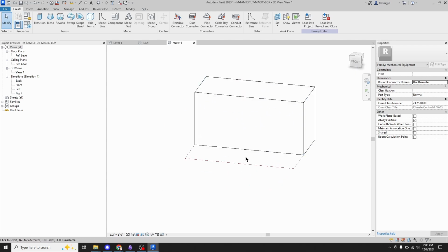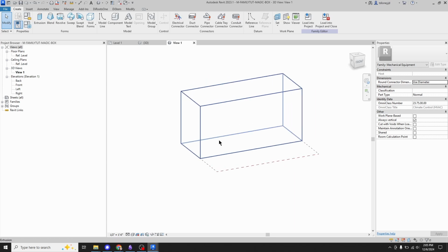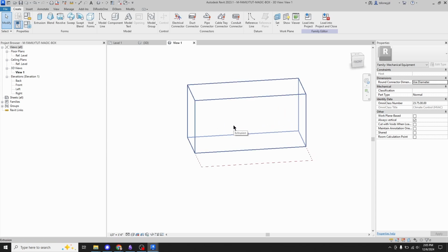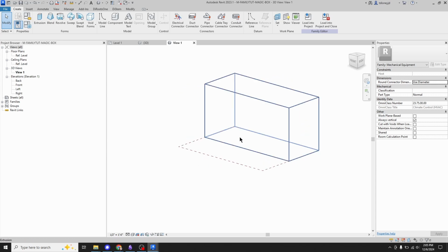Okay, so what we've decided we need is duct connectors on the bottom here and about here. So return and supply. We don't really have to model the outside air intake, the economizer intake, because you don't connect a duct to that. But we want our duct connectors for return air and supply air, right?